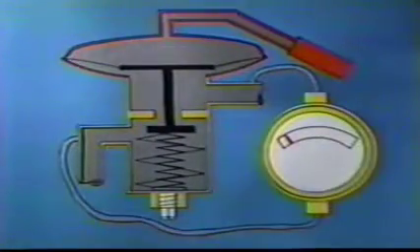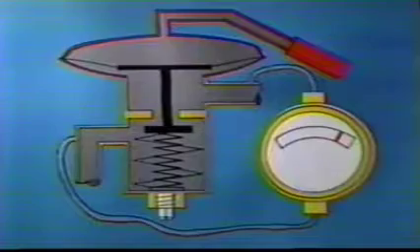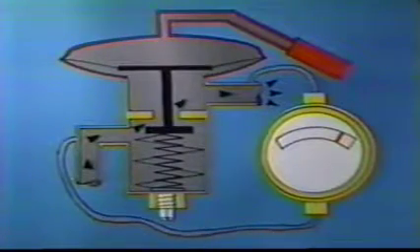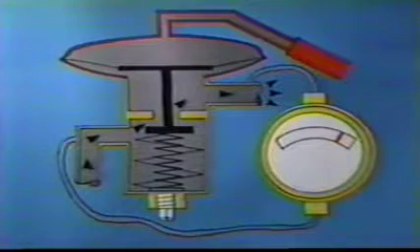Were there not a pressure difference across the valve, there would be no flow through the valve. The higher the pressure difference, the greater the rate of flow. It's important to note that it is the pressure difference at the valve that determines flow. It is not, as is commonly thought, the difference between discharge and suction pressure measured at the compressor. All pressures in a refrigeration system are a combination of the refrigerant pressure, the pressures generated by the compressor, and the pressure drops that occur in the piping and components carrying the refrigerant. All of these factors must be accounted for in determining the actual pressure difference at the TEV.